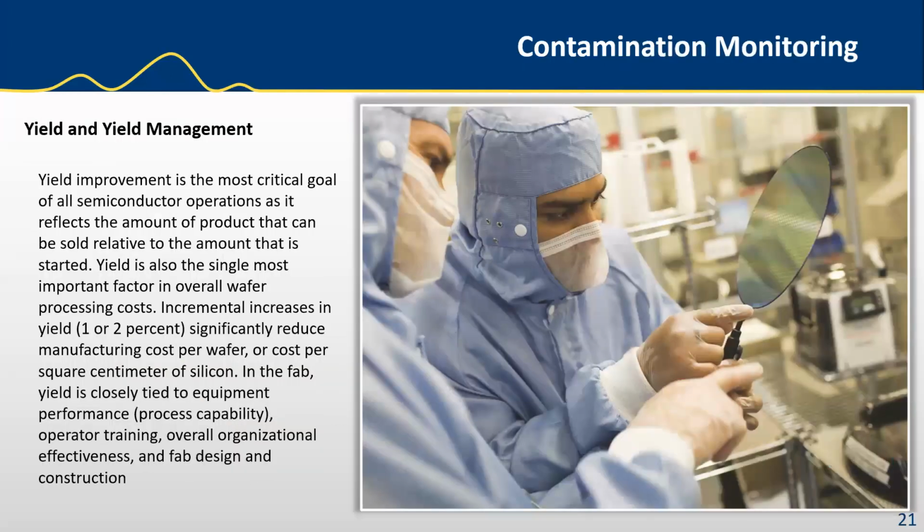So line yield and defect density are two of the most closely guarded secrets in the semiconductor industry. Line yield refers to the number of good wafers produced without being scrapped, and in general measures the effectiveness of material handling, process control, and labor. Die yield refers to the number of good die that pass wafer probe testing from wafers that reach that part of the process. It's intended to prevent bad die from being assembled into packages that are often extremely expensive, and measures the effectiveness of process control, design margins, and particulate control.